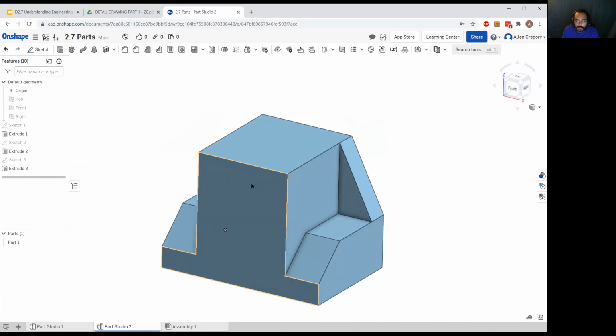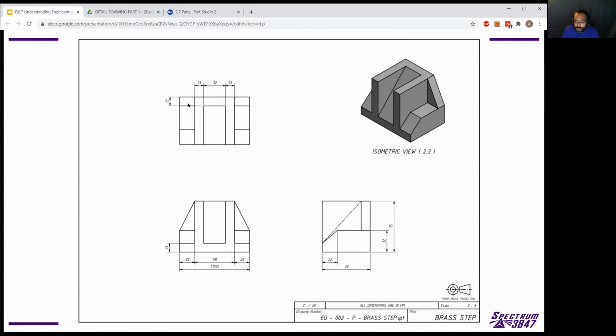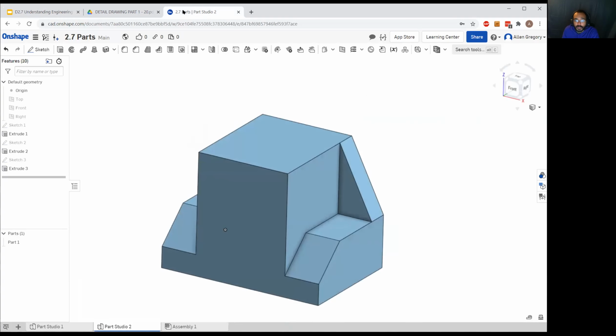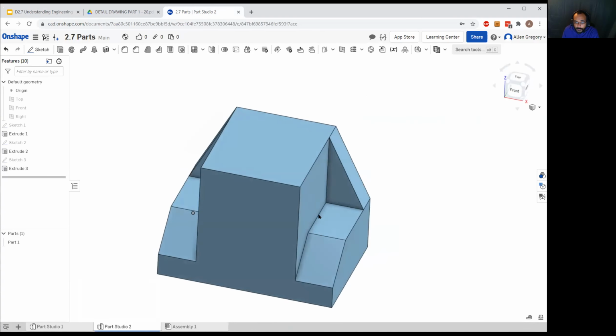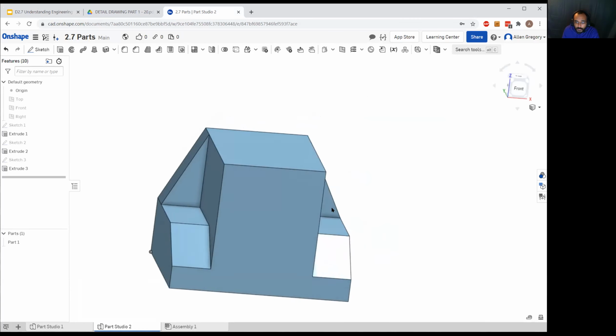Okay, so the last little bit is a little bit trickier. We have this hidden line in here that can kind of show what this looks like. So we know it's the same bottom point down here. We know it's the top point up here at 13. And we want to remove all this middle section. There's a few ways we can do that.